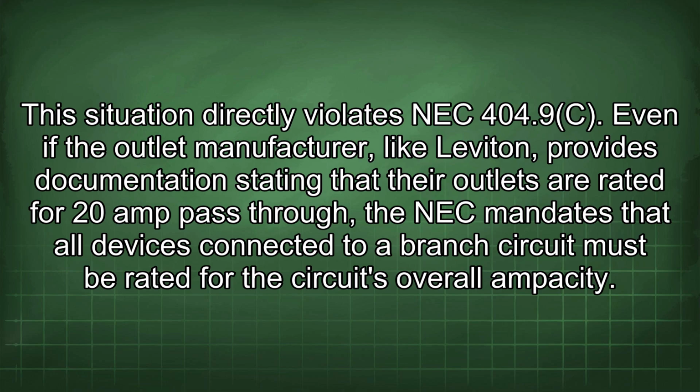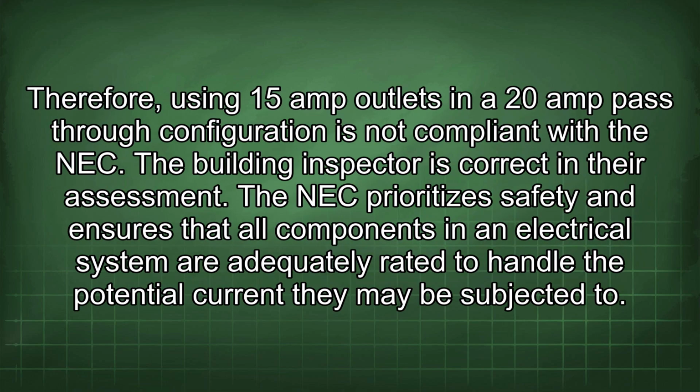Even if the outlet manufacturer, like Leviton, provides documentation stating that their outlets are rated for 20 amp pass-through, the NEC mandates that all devices connected to a branch circuit must be rated for the circuit's overall ampacity. Therefore, using 15 amp outlets in a 20 amp pass-through configuration is not compliant with the NEC. The building inspector is correct in their assessment.